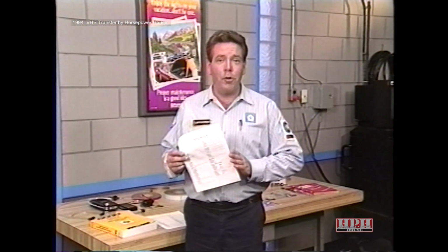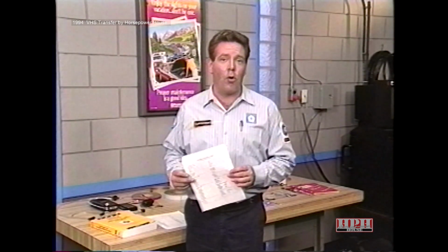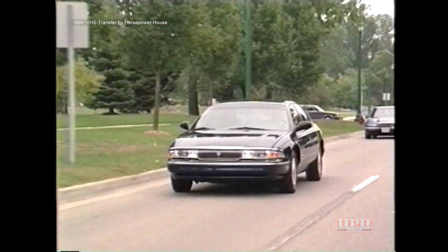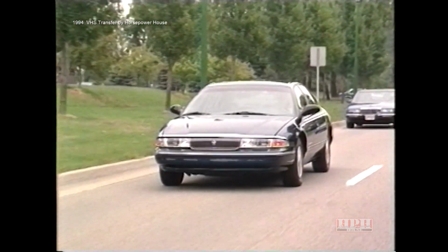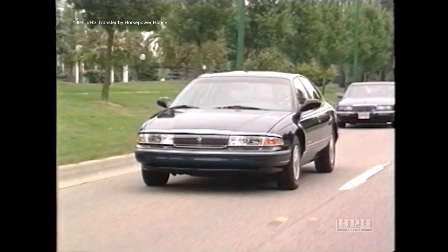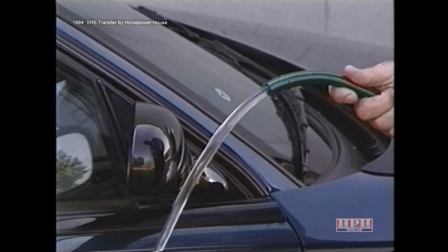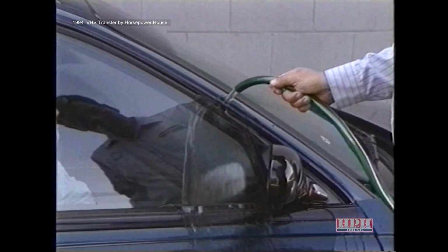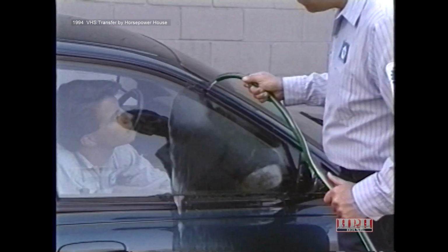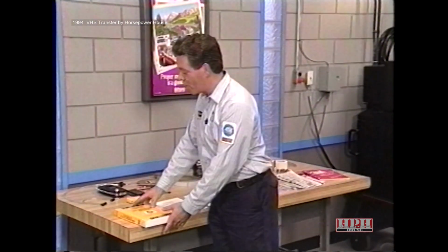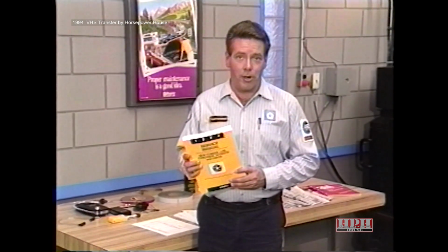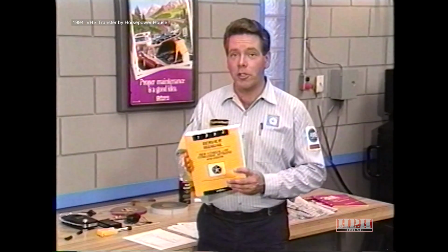So, once you've reviewed the information on the customer feedback form, your first step is to verify the customer's complaint. For wind noises, you'll need to take the vehicle for a road test and simulate the conditions under which the problem appears. For water leaks, your best bet is to water test the vehicle, which we'll explain in a few minutes, to be sure that a leak is occurring. Your service manual contains several good suggestions for simulating a variety of conditions in which a water leak may occur. And you'll need to refer to the service manual to answer one of the quiz questions in your reference book.